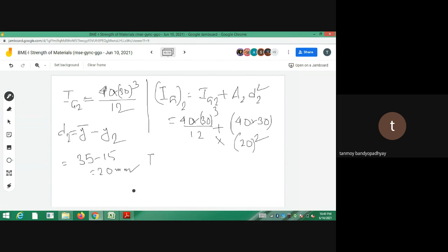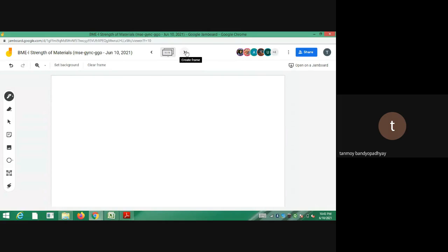So what is the total moment of inertia for the T section about x0y? So that is IG, which will be equal to the contribution from the first element plus the contribution from the second rectangle. If you calculate, you will be getting the value to be something like this, which I had done, like 990 into 10 to the power minus 9 meter 4. Just wait a minute.